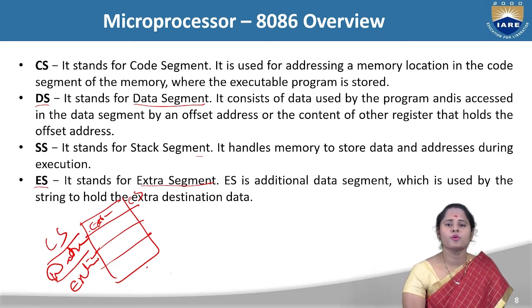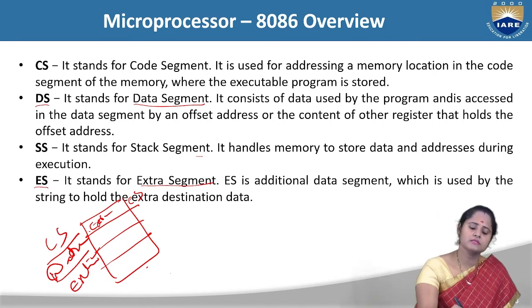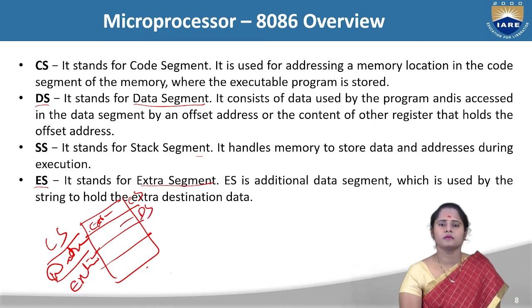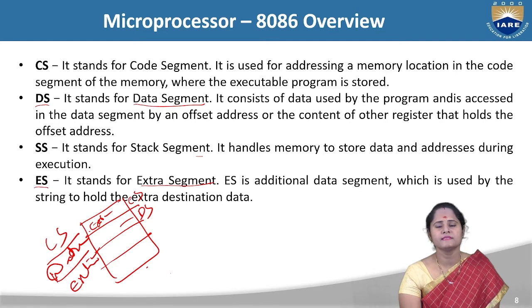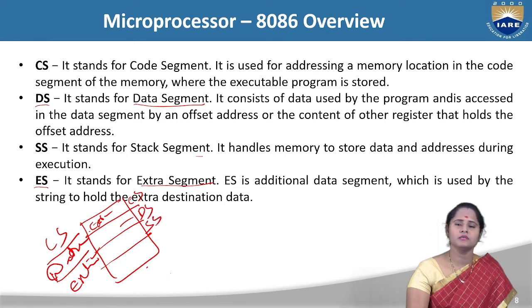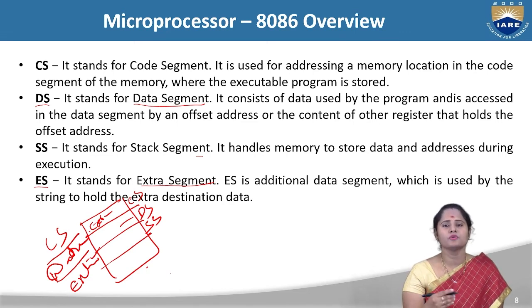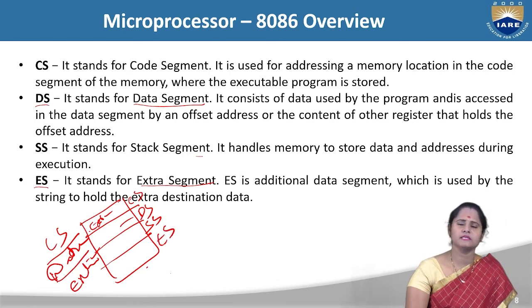Or if my microprocessor needs to execute some data, that data can be stored in some memory location present in the data segment. So we are telling my processor beforehand that data will be present in the data segment, the code which I need to execute is present in the code segment, and the stack related operations can be present in the stack segment. And the extra content which I need to store for future purposes, or execute later, can be present in the extra segment.